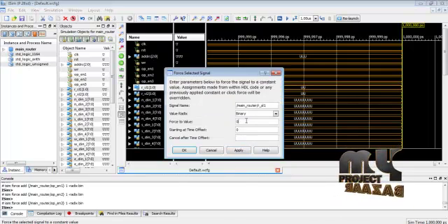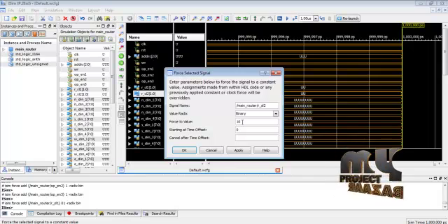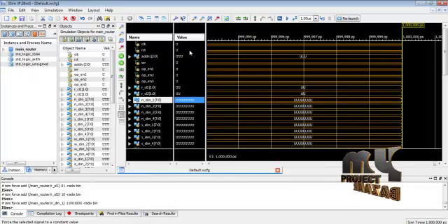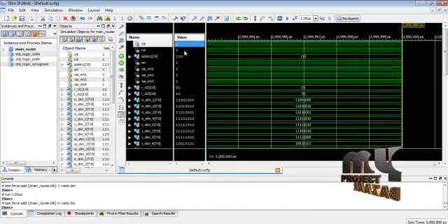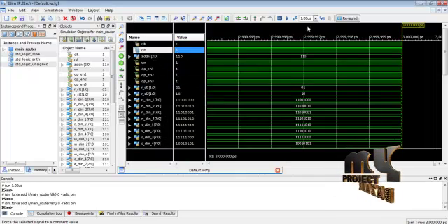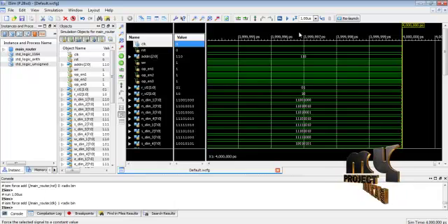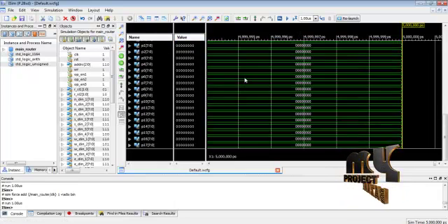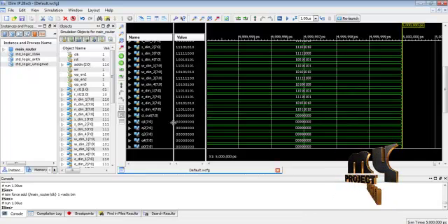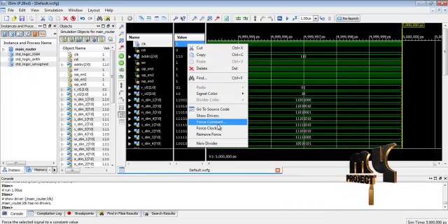Then apply the selection based logic. Then any binary data input is applied for the overall architecture. Then activate the reset function and apply the clocking section. Then deactivate the reset function and apply the clocking function in every architecture design. Then transfer the data for each 2x2 router architecture design and get the output for another result based on the selection lines, passing the results and applying the final output results for our clocking based output logic in our NOC architecture designs.